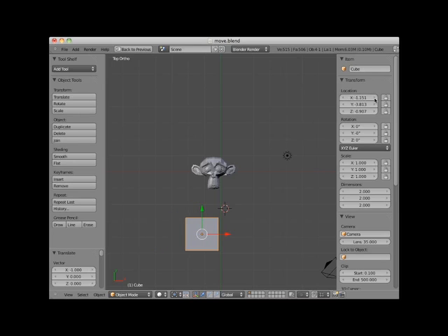I will click and drag the arrow control to the left of the Y location, and I can move the cube. I can also just type in an X, Y, or Z location. Here I will set the cube at 0 X, 0 Y, and 0 Z. I'll rotate the 3D display into a user orthographic view.